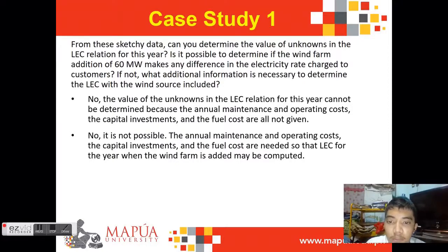No, it is not possible to determine if the wind farm would make any difference because the information given is insufficient. The additional information needed are the annual maintenance and operating costs, capital investment, and the fuel cost, so that the LEC for the year when the wind farm is added may be computed.